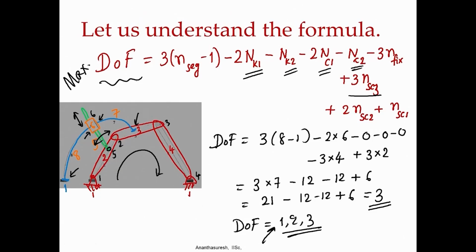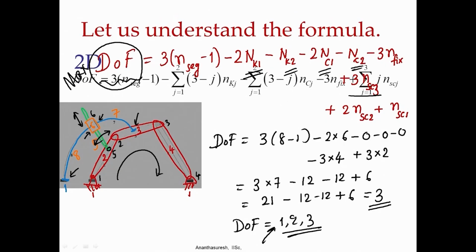But this formula that we have as modification for compliant mechanisms will give you that maximum number of degrees of freedom. Degrees of freedom definition still holds, that is minimum number of inputs required, but degrees of freedom itself, now we have an upper bound on it or maximum value. Whether you give 1 input to this mechanism or 2 inputs or 3 inputs, it will give you deterministic motion. That is what we want to have in terms of mobility analysis.